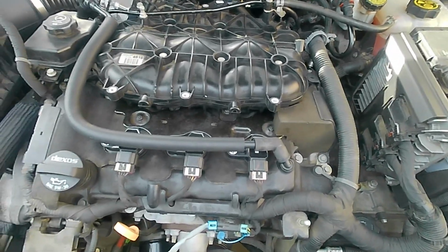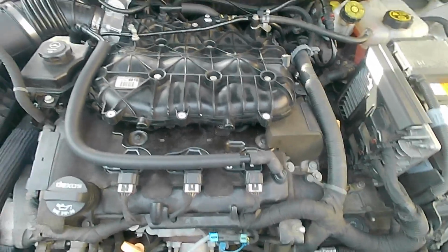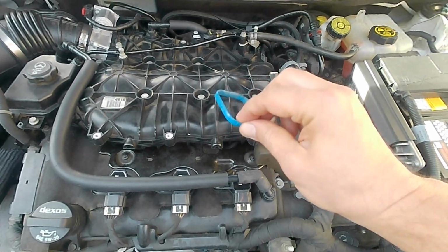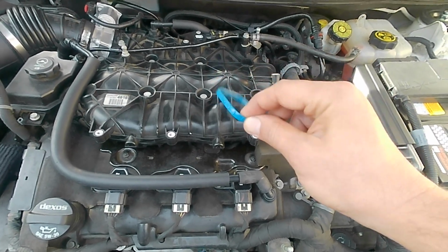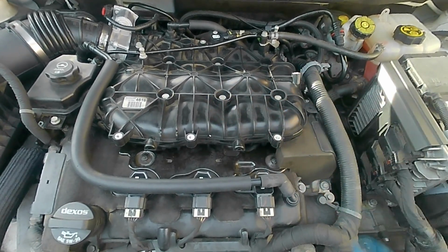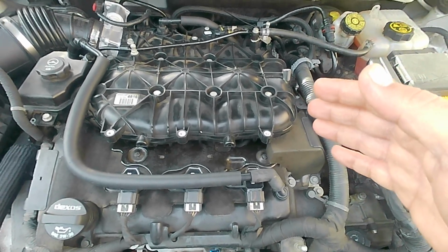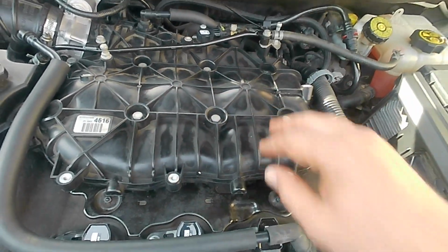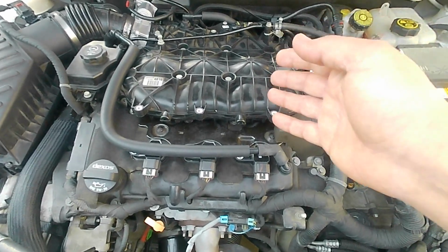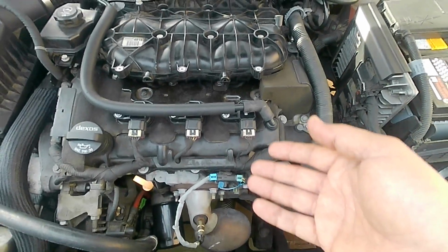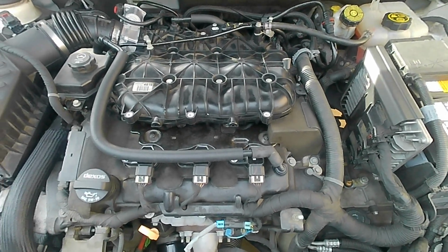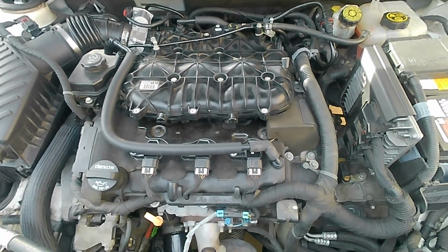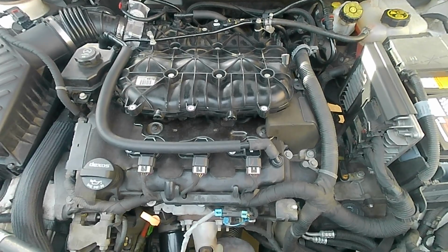So this is the lower intake gasket, and then this part is the upper intake gasket. A lot of people miss to replace that, and it's the one that causes lots of issues. And then the other step is to clean the intake valves. We will go ahead and go through the procedure to clean it, and also, like I mentioned, we will be replacing all the oxygen sensors, the O2 sensors. With that, hopefully we can get this issue resolved. So with that said, let's go ahead and start it.